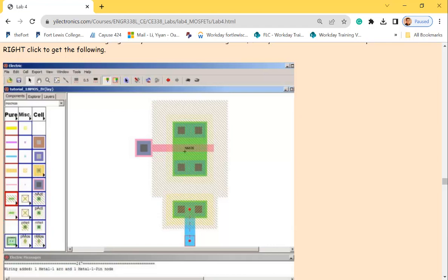Okay? Two vias. And that's the terminal of the NMOS, which is going to be N plus over here, N plus. Okay, and it connects to the top metal layer. So the via will drill a hole up, and then you can run metal one.